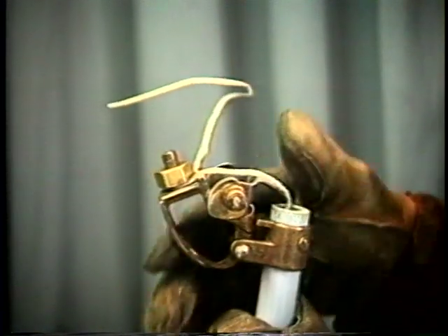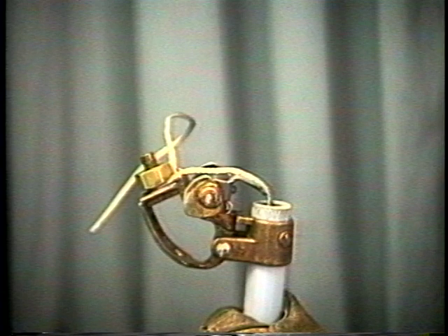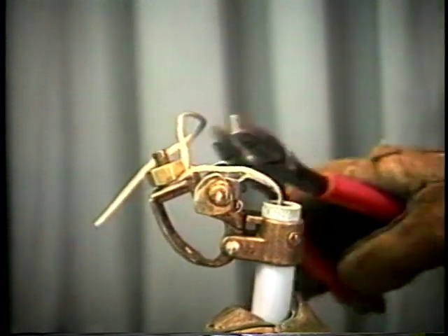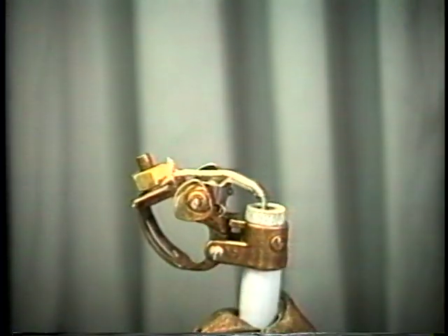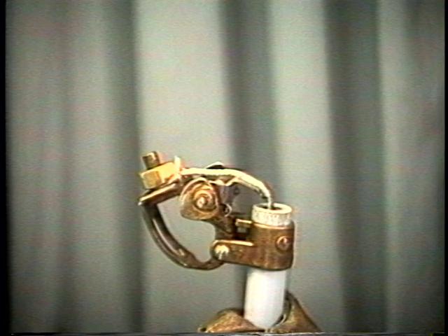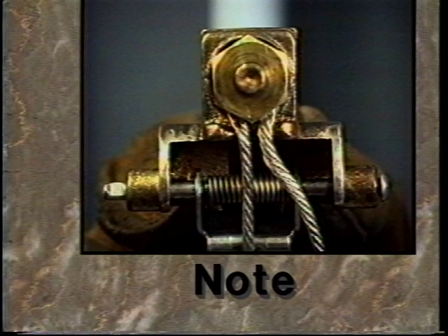The final step is to inspect your work thoroughly. Make sure the fuse is properly installed. If all appears to be in order, cut the excess of the fuse tail as close to the nut as is possible. The barrel is now armed and ready to be installed in the cutout. Note: the tail of the fuse should not be wrapped around the post, simply looped over it.